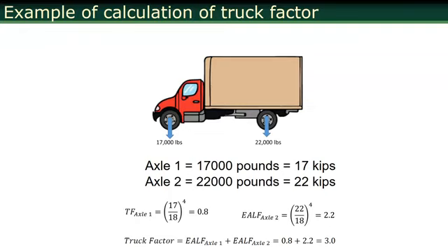We did a pavement ME analysis on this very recently. Mechanistic-empirical pavement design guide. We used the pavement ME software. So we used, let's say, a single truck at 18,000 pounds, and you put 100% of all the trucks on that road at 18,000. And then we doubled that load, and kept doubling, and kept predicting the fatigue cracking using the different axle loads.